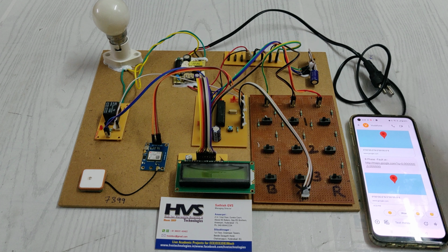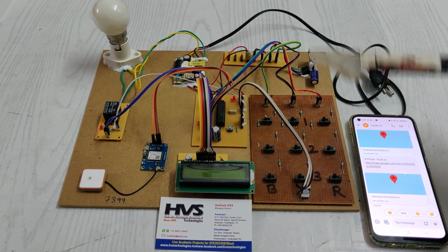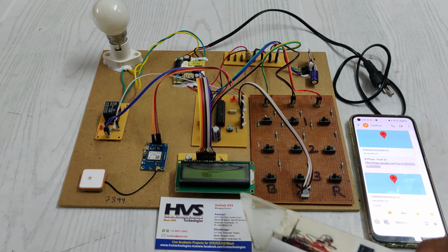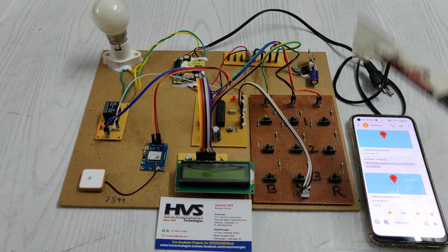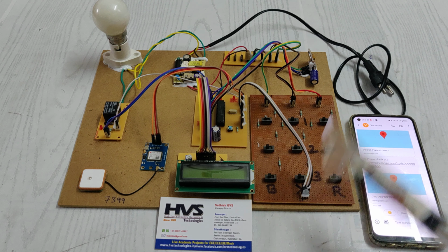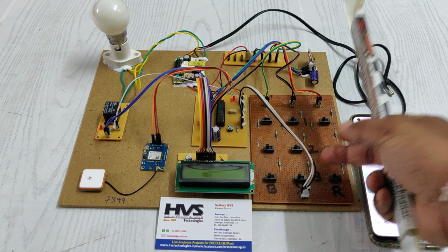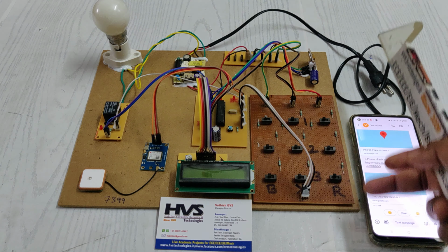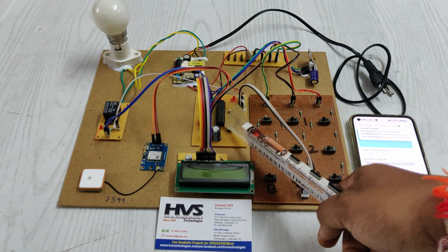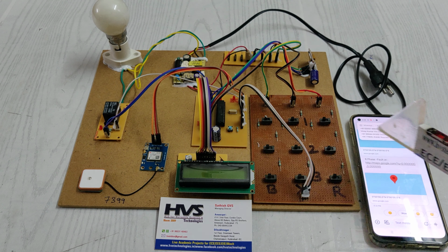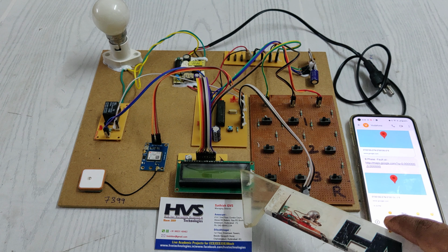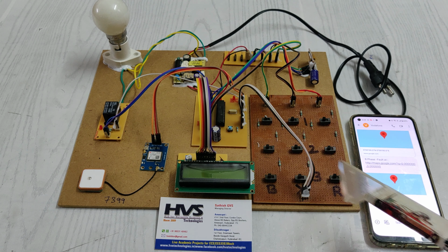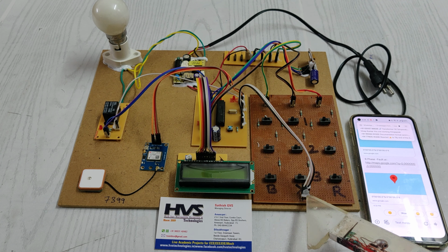Whenever a short circuit occurs, the particular voltage will drop at the receiving section, where, as we discussed, the system is placed. These are the checking voltages in the respective phase outputs. In the microcontroller we provide the conditions along with the voltage dropping cases. Whenever the respective case is executed, it will be displayed on the LCD along with the fault identification in the respective phase, as we are measuring.